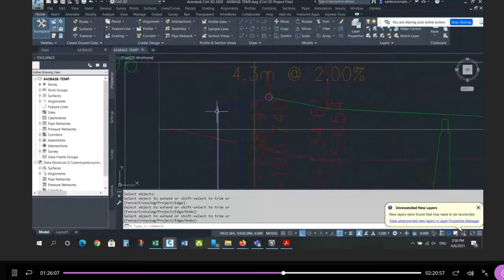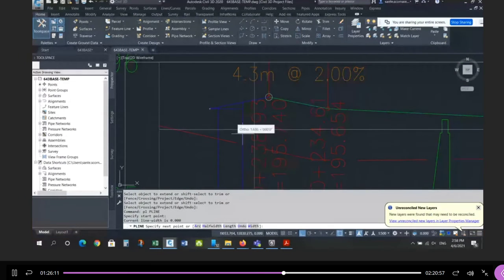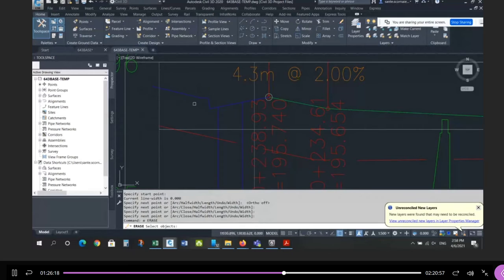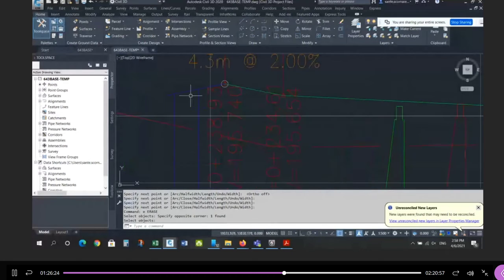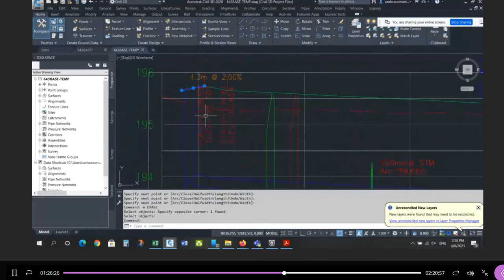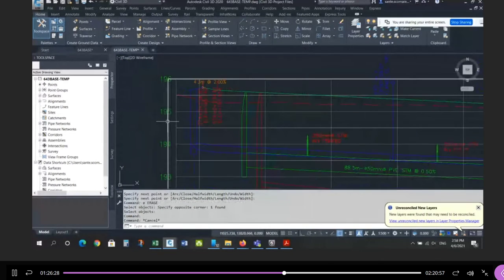Right, and then really, if you want to complete the picture, you should draw, I'm not going to do it accurately, but you should draw the boulevard, top, back, a curb, and the 2% line going up to the street line, right? That's not accurate, but that's missing. That should show as well, just to complete the picture. Definitely you need this, otherwise you won't be able to draw the top of the valve chamber.